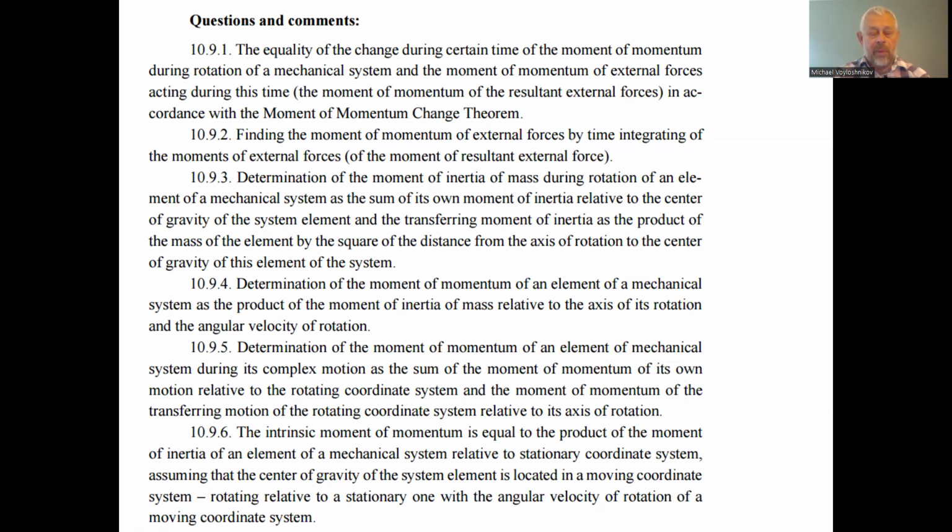10.9.2, finding the momentum of external forces by time integration of the moments of the external forces, of the moment of the resultant external force. We can just use the momentum change theorem. On the left we have the derivative of momentum, which is a product of the characteristic of the rotational inertia of the elements of the mechanical system and the angular velocity of the rotation.